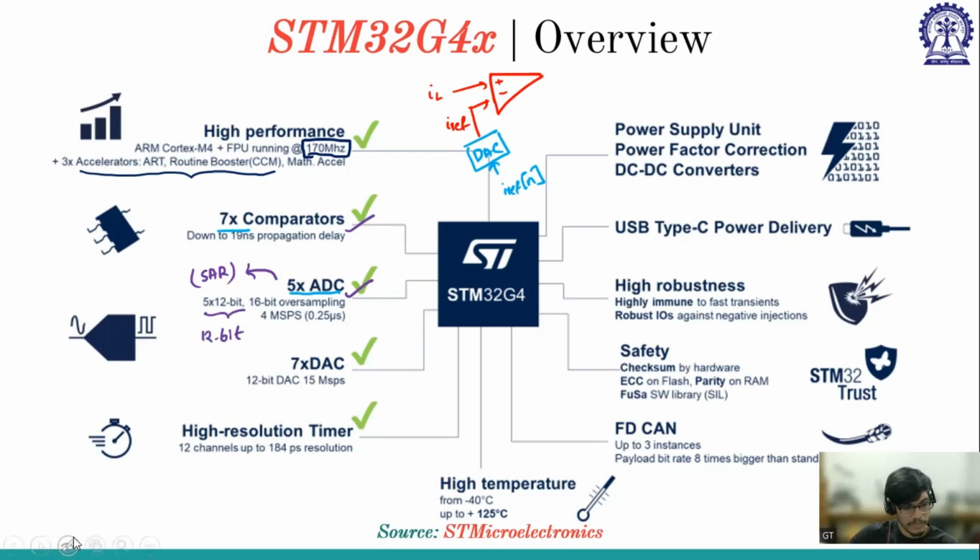I have a doubt. Yes. Sir, which is faster: is FPGA quicker in computations or the microcontroller? That depends upon the frequency, right? This one is operating at 170 megahertz, and the FPGA might have 100 megahertz, or some FPGAs have even more, up to 500 megahertz. And here the ADC is the SAR ADC. If the clock frequency is the same in both, which computes faster? Then, if the clock frequency is the same, both of them have almost the same performance.